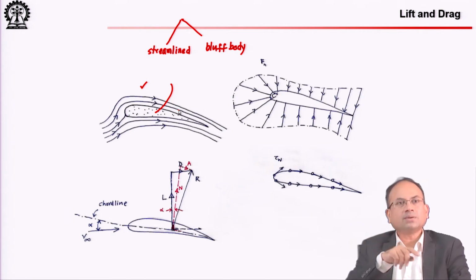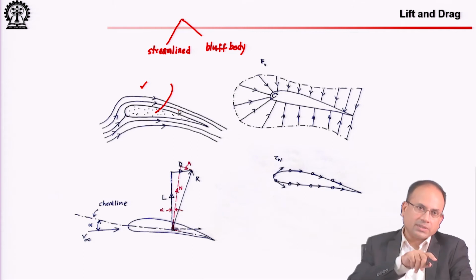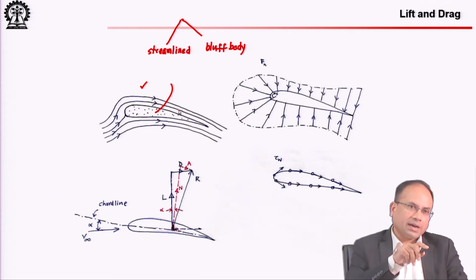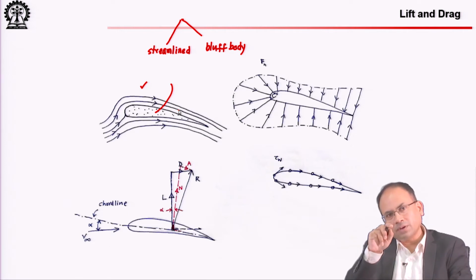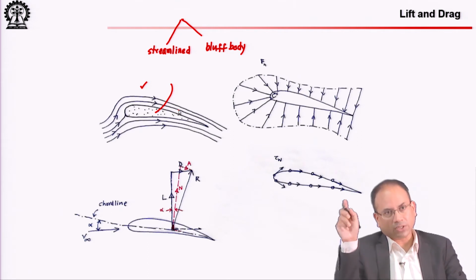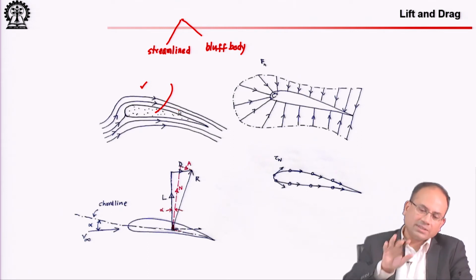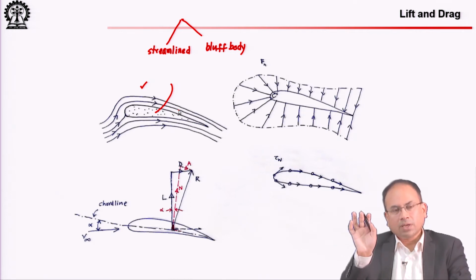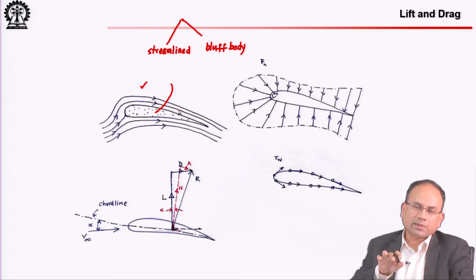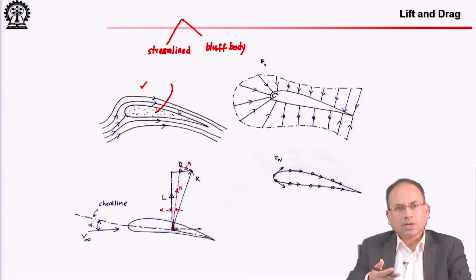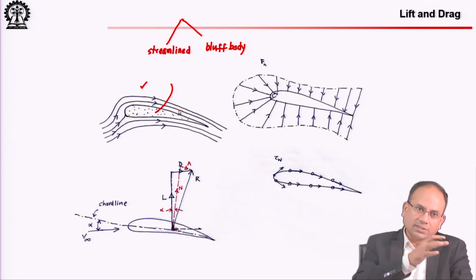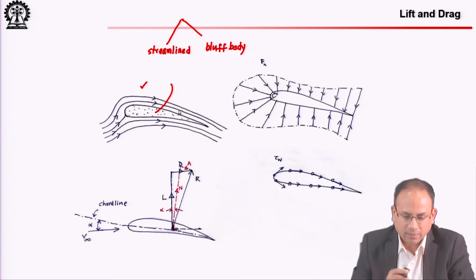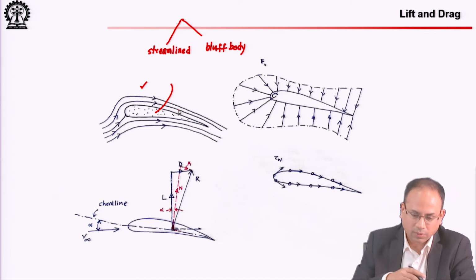Right now we are discussing Bernoulli's theorem, and in the last class I had come to the point where I said that the gradient of the total head is equal to 0 if the flow field is steady and irrotational. So, we will start with that point and we will see some intricacies of what happens when the flow field is not steady, what happens when the flow field is rotational, etc., to Bernoulli's theorem. But I am creating a context for students who are coming to this video lecture by itself without having the sequence of videos that many of the other of you are following.